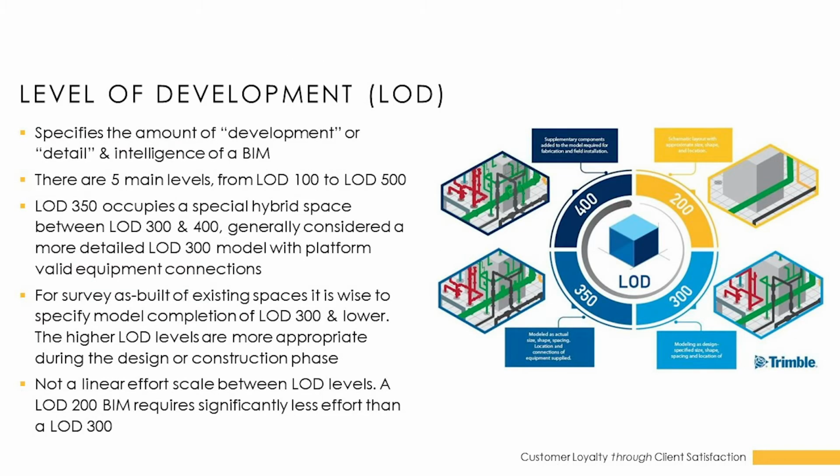So level of development, this is that term I was talking about. I defined it earlier. I've been throwing it around a little bit here. Let's talk a little bit more about this because there's a lot of confusion in the industry about LOD, or level of development. It specifies the amount of development of your model, or in common vernacular, the amount of detail of the model. Remember I said they're not quite interchangeable. You can kind of think of detail as, well, how close does a modeled object really come to looking like it does in real life? Whereas with development, you might lose a little bit of that detail, but what it gains is